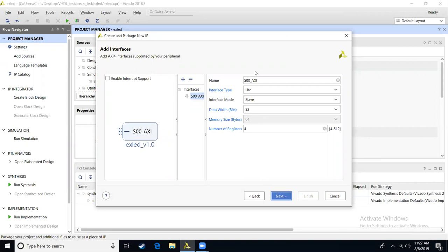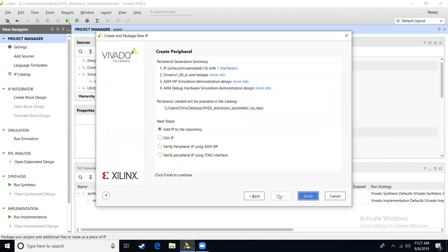Right now, we can leave all of this data standard. Later, as you do more advanced items, you may want to change the number of registers. The registers are how your CPU will write into your custom interface. The default is 4. All we'll need is just 1 in this example. All right, we're going to create it. What's our next step?